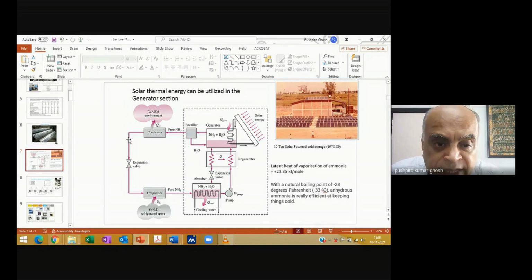Now this is known as an expansion valve. What it does is that it expands the liquid into vapor, but not all of it, partly. The expansion is effectively releasing your pressure. Your pressure is now getting reduced, and so you formed a lot of vapor. That vapor is of course straight away going to go into this absorber.